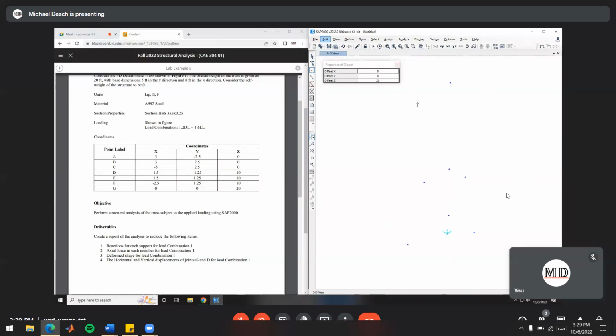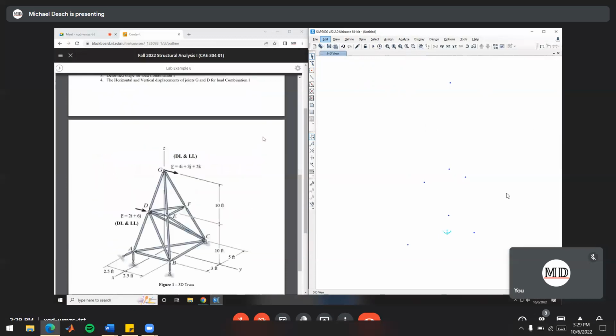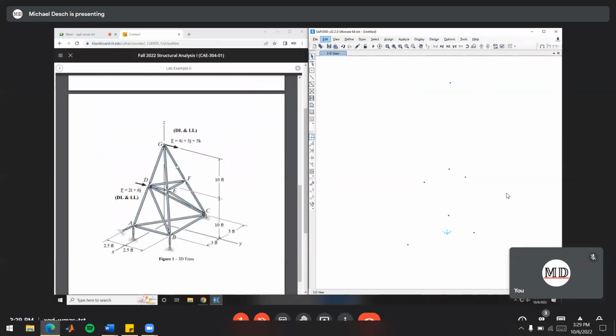So now we're done with this tool. Let's press escape so we can exit out of the tool there, so we're not going to accidentally put in any extra nodes. Now what I want to do is draw in everything between all the right nodes, because you see these all have labels, but we don't have any labels over here. We're going to rotate our model so that our coordinate system lines up with this coordinate system over here in the picture we have.